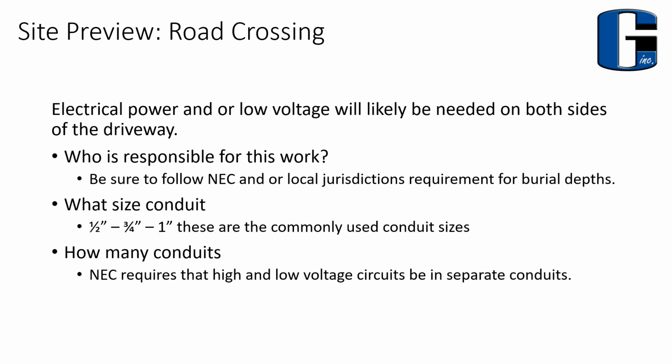Very important there. Residential road crossings typically require an 18-inch minimum cover, and a commercial roadway would typically require 24-inch roadway cover. So you can't just trench 6 inches across the driveway and expect to bury conduit and meet electrical code. Conduit sizes. In our industry, we're typically using 1/2, 3/4, 1 inch. These are the most common sizes. Larger conduits might be used for longer, more heavy-duty applications and different kinds of needs.